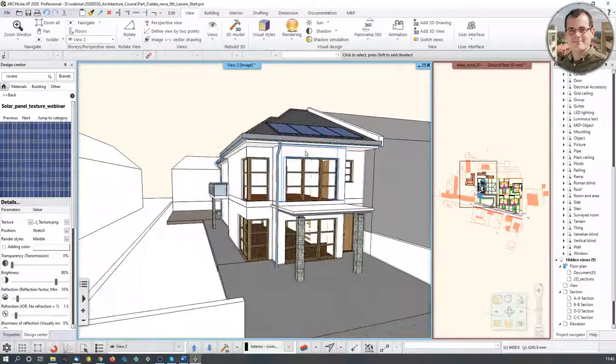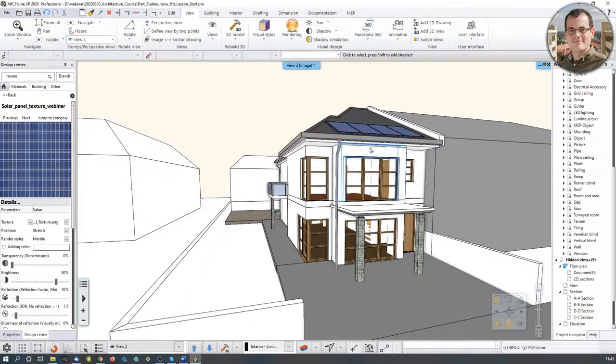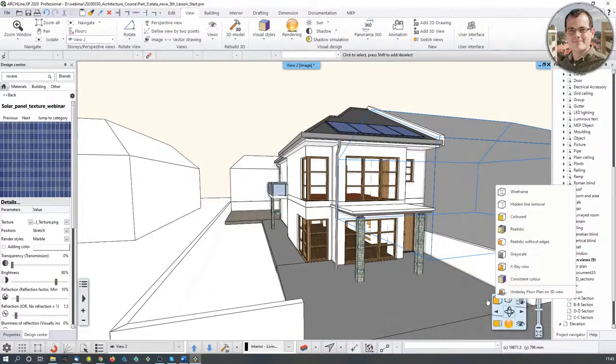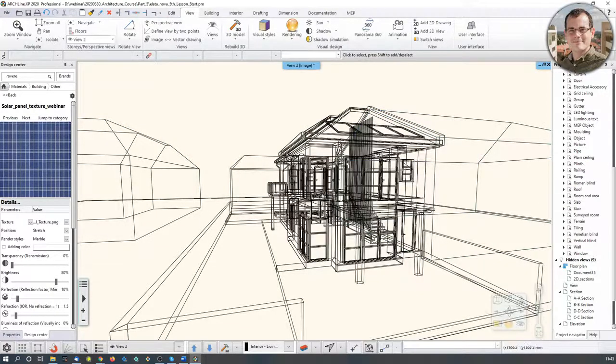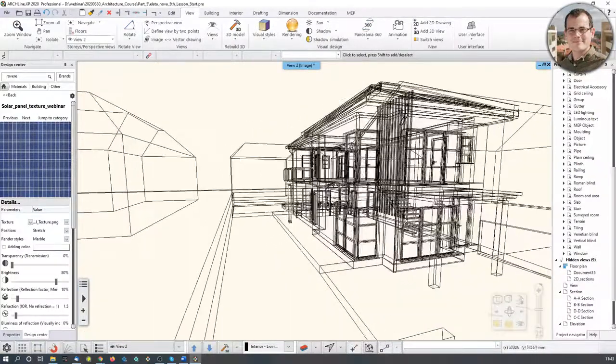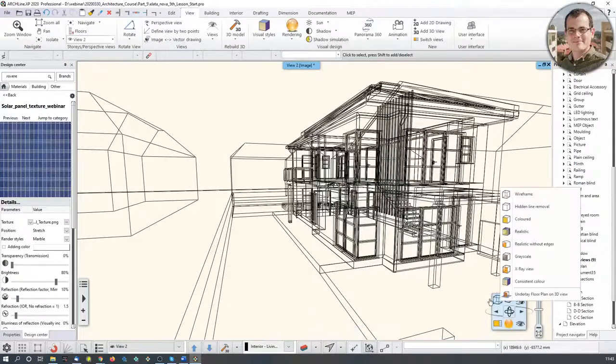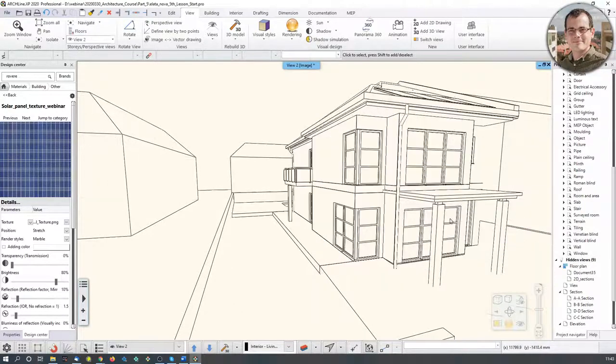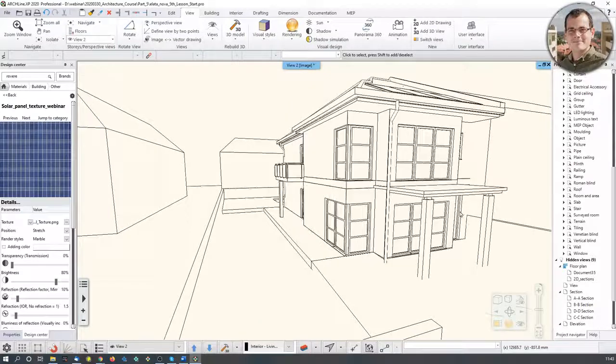And one very vital thing that we haven't talked about is the view and representation style. So how do we define how we want to see this model? Actually, there's a style switch over here, 3D preview mode. Let me talk about what this means. I talked about this briefly before, but repetition never hurts. So wireframe would give you an X-ray vision, shows you the whole thing, which if you have many things, could be very confusing. So maybe you should go with a hidden line removal, which gives you this paper cut model.